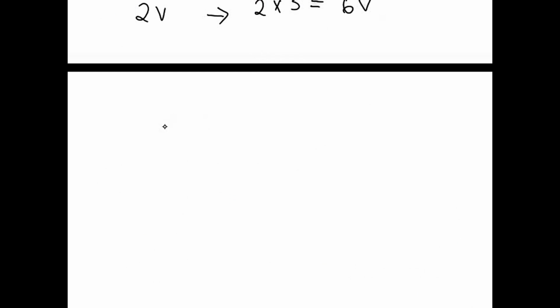I'll say voltmeter V3, the potential difference across light bulb C, is equal to the total potential difference, which we found to be 6 volts, measured by voltmeter V1, multiplied by the resistance of light bulb C divided by the total resistance, which is RC plus the resistance of the parallel connections.